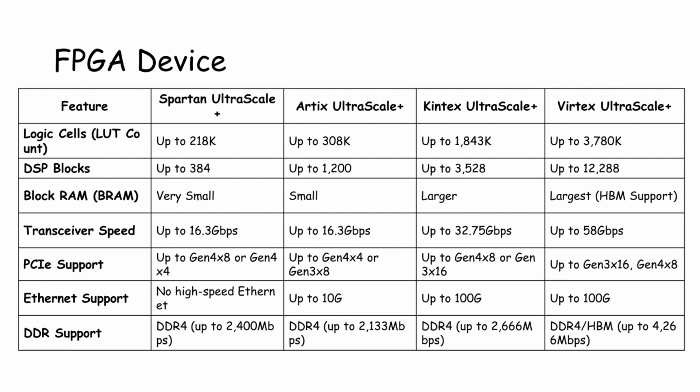One of the most important factors in device selection is resource fit. The FPGA must have sufficient logic, memory, and I/O to support your design. In addition, the device should be readily available on the market. That means choosing a part with good supply chain stability, reasonable cost, and minimal lead time. Ideally one that's already widely used by many companies in the industry.